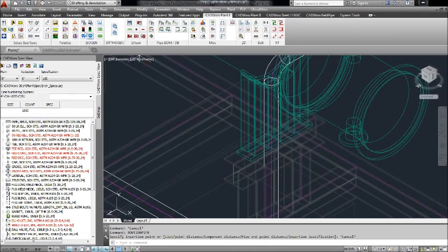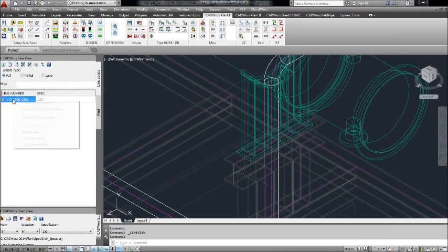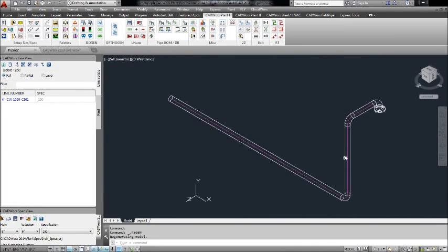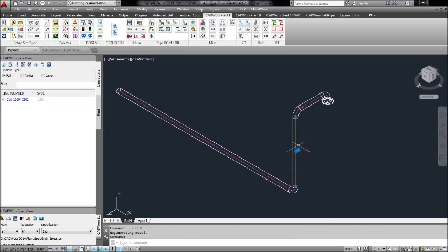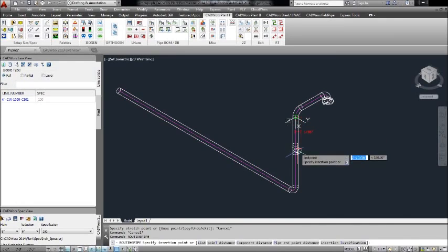I've got a little bit of congestion there, so let me take a moment to isolate that line. This is another really nice tool in CADWorx. We'll isolate by line number, and now I've cleaned up all of that mess that I was looking at so that I can work on this line. That's really good practice for CADWorx. Once you have your overall layout done for a given line number, you can go into your palette and isolate it and then work on all your inline components.